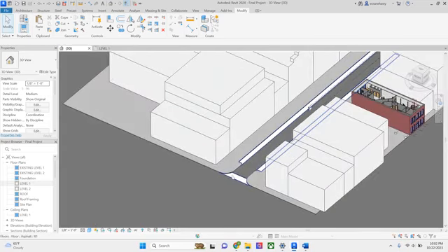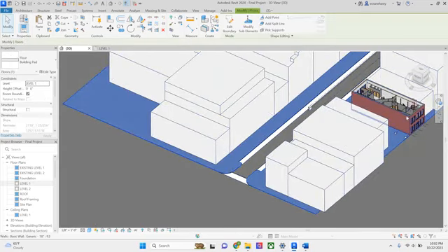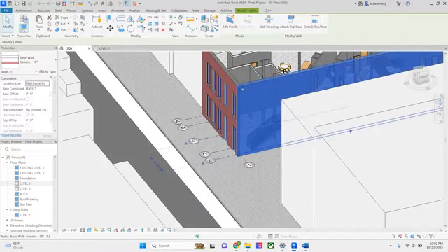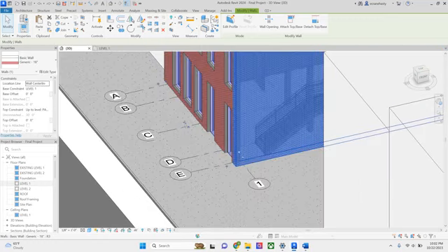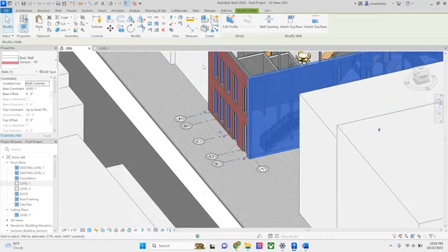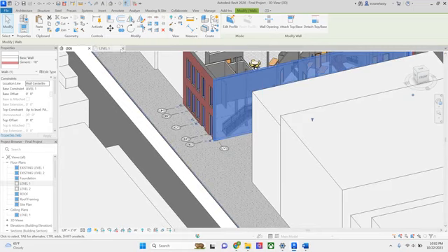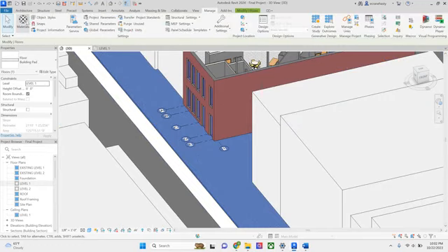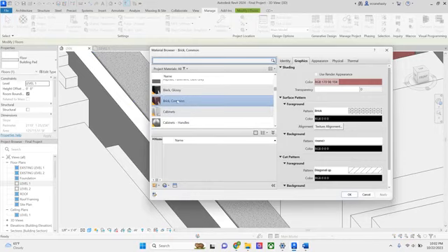Also, just for example, you notice that I clicked brick common, which is just the common lay, the common orientation and run of brick. So if I make this material on this building and this material here that I've selected both the same material, that means if I change this, then they both change. And I hope that that makes sense.